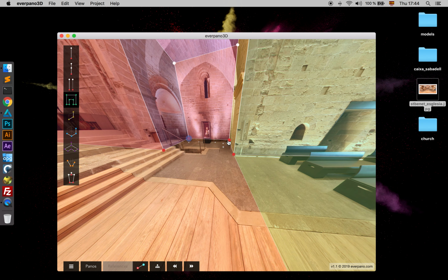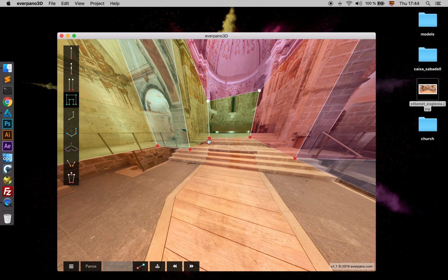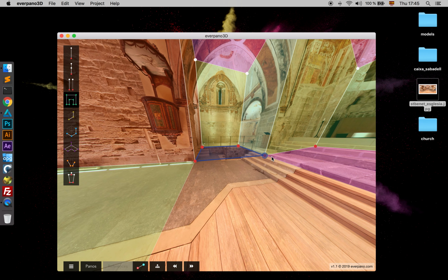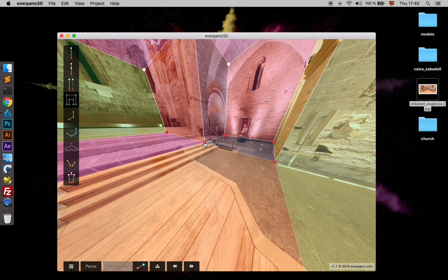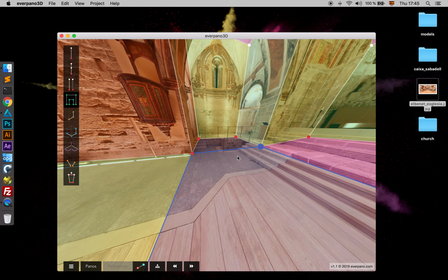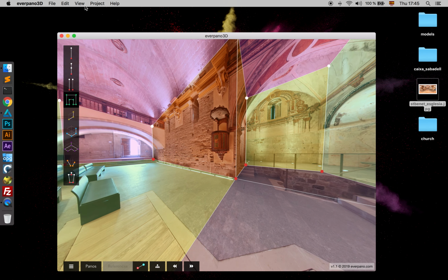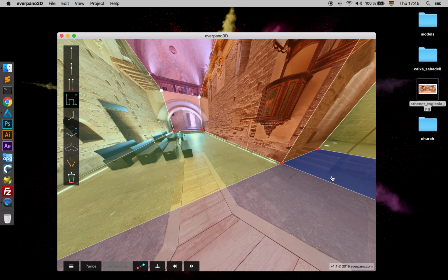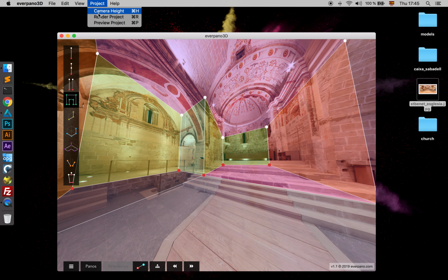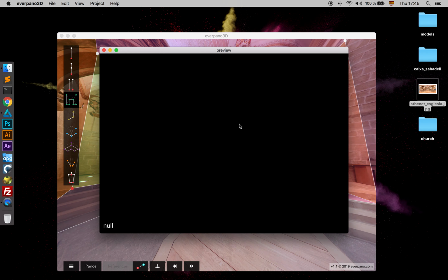In that case, I'm going to make small quads. So when you make a quad with 4 points, you should never worry about the size, because a quad is composed of 2 triangles, so there is no triangulation process here. Okay, so now we have our very simple model done.